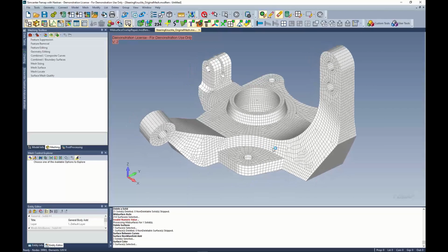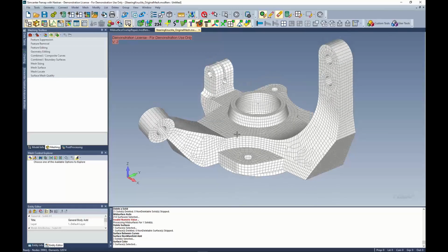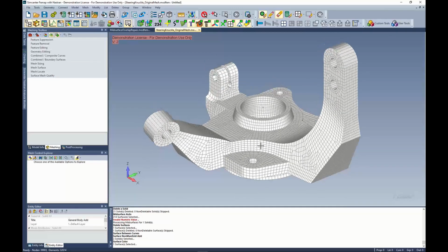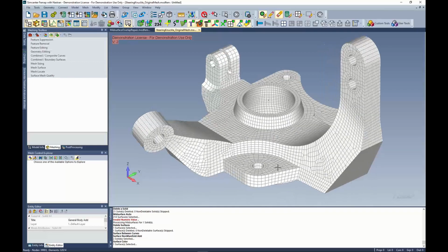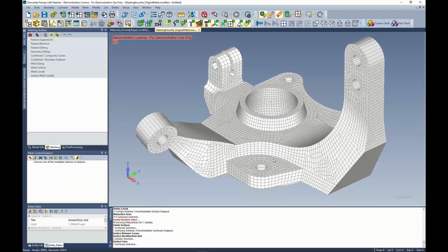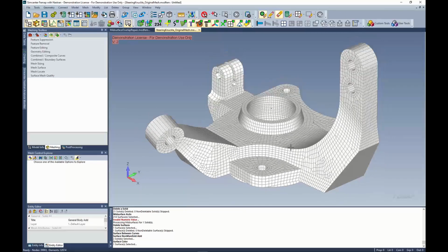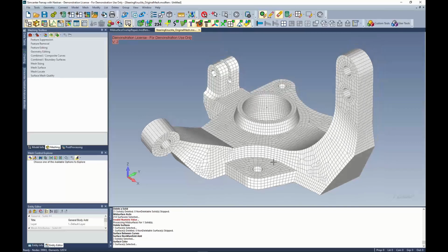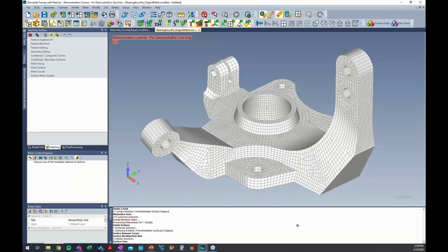But the solids, like if you wanted to hex mesh this, you have to slice it up into hex meshable solids. With a TET mesh, you don't have to slice it up. You can just bomb it, mesh the whole thing. But because you have to slice it up, then you have to match all these surfaces to make sure the mesh propagates. And previously, if you did that automatically, it'd be hard to tell which one is actually mapped up together.